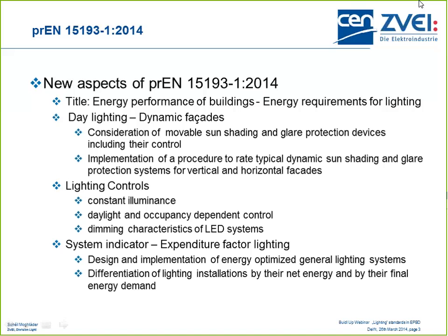The next thing which is also new in this revision of the standard is the lighting control. So this means that we take this into consideration to have a constant illuminance level. And this is especially more and more easy to do with the new products on the level of LEDs.